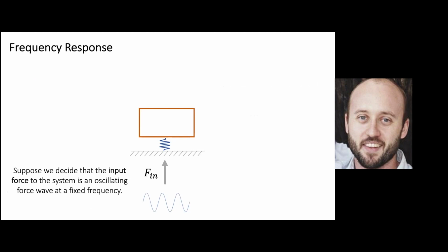So when we're talking about the concept of frequency response, which we're going to jump into a little bit later when we start talking about accelerometers, going back to that discussion of vibration-based condition monitoring, we can start to measure a frequency response of a system if we give it a known input at a known frequency. So now let's consider I'm going to give it a forcing function. I'm just going to oscillate the bottom at a specific force magnitude and at a specific frequency. So this would be like an oscillating sine wave.